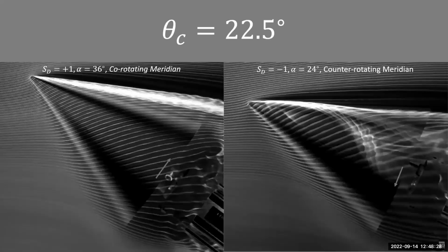Okay, I just wanted to leave a few comments on the persistent signatures of boundary layer instabilities. These are the angled wave patterns that I've indicated. And also, we've noted that for streaklines that get ingested deep in the boundary layer region, they're following the direction of rotation. So if we look at these arched or arced streaklines, these are following the direction of rotation because they're nearly attached to the surface. They're marked by these very small scale curly signatures. And these are signatures of the spiral wave instabilities that we expect to see.